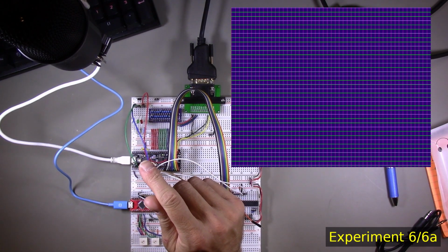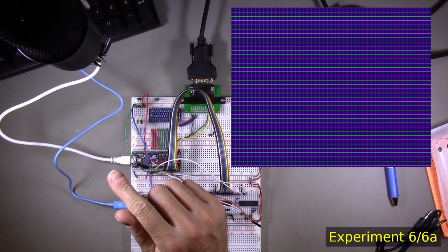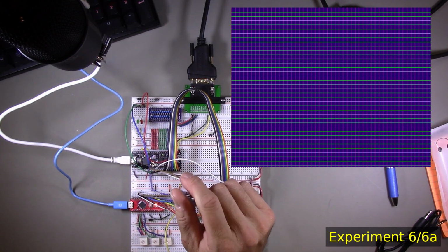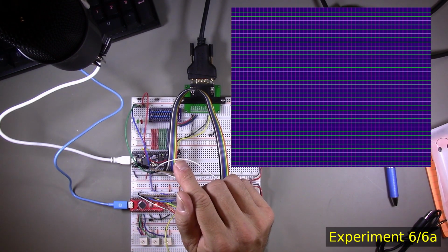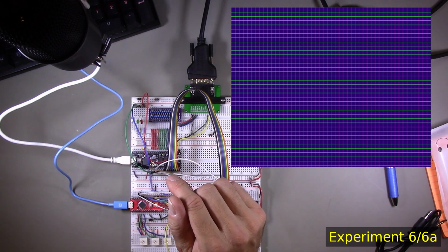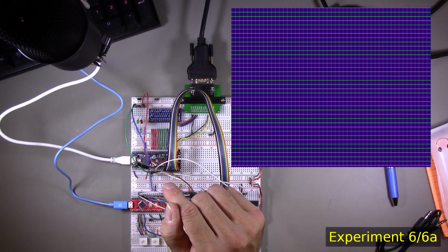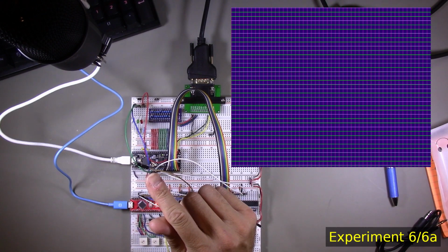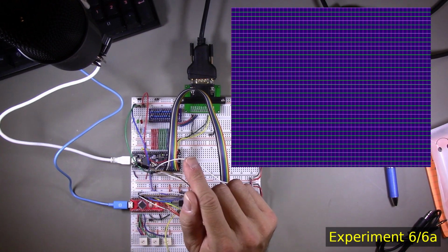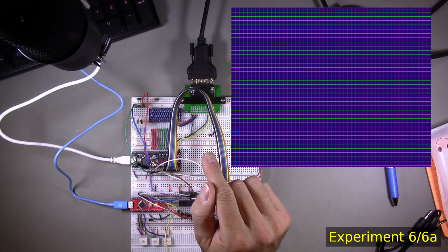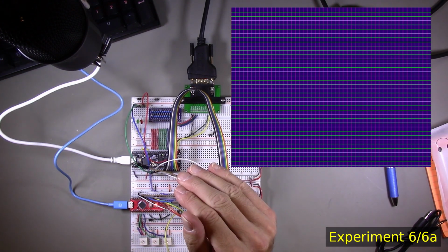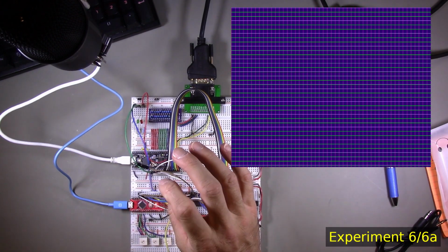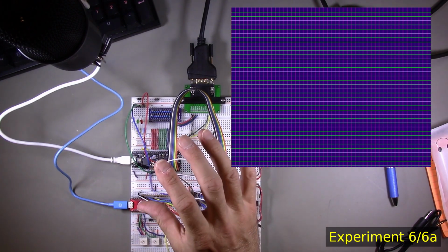So for example, I changed the pixel output process so that it used a particular color every time the vertical count was a multiple of 16, which means it should be at 0 and 16 and 32 and so forth. And rather than seeing that row of pixels right at the top of the screen being rendered in that color, it was actually at pixel row 15, I think. It was much further down. So there clearly was an issue where the horizontal and vertical counts weren't accurately being reflected.